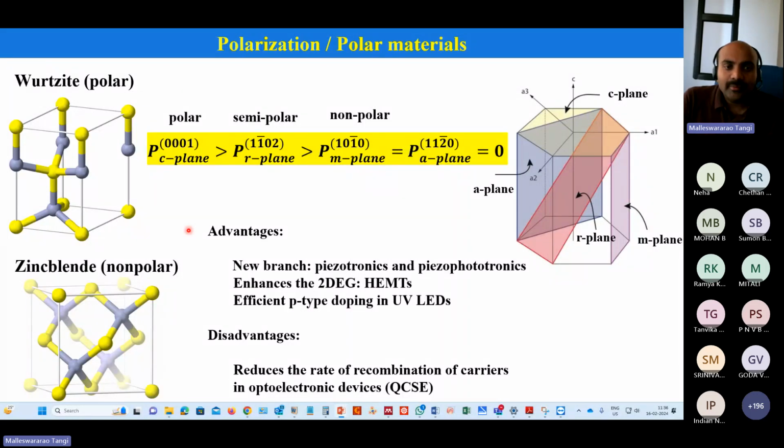This III-nitride material system has a specific and unique property: it exhibits polar nature. These are available in wurtzite or zinc blende crystal structure, but the most thermodynamically favorable structure is wurtzite. Several researchers have tried to grow the zinc blende structure, but they were not successful because it is difficult to get this zinc blende phase. The zinc blende phase is good for optoelectronic devices because it doesn't exhibit any polar nature, and this polarization kills device efficiency.